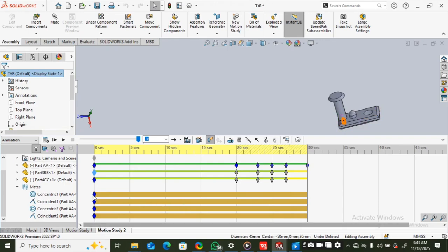If I click this section, this place, click yellow, the mate connecting this nut to this plate below is the mate you see over here, followed by the respective mates that were given to it. So a model will move following the mate that is connected to the component you see over here. That's another thing I need you to know in SolidWorks animation. It's a basic that needs to be understood before we continue.